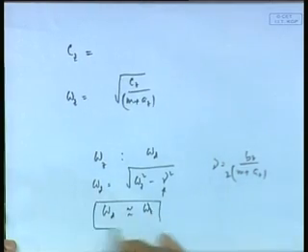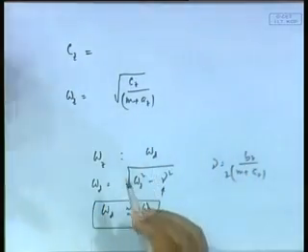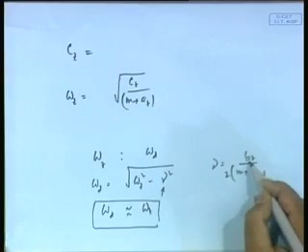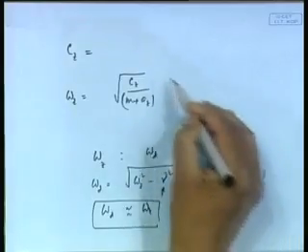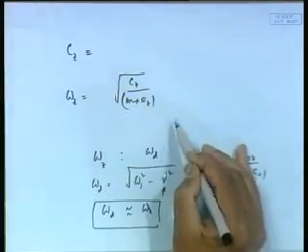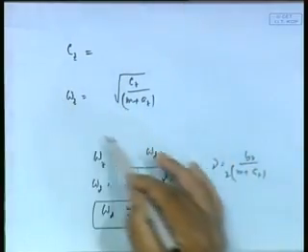So, for all practical purposes, when we study natural period and we say resonance, as you know, when omega e is omega z, it is resonating, that is this peak value. So, we can estimate the resonance by simply taking omega d to be omega z. So, our focus becomes omega z rather than omega d, which is also very useful for me, because if I had to do omega d, I had to get nu, which means I had to know Bz. Bz is much more difficult to estimate. This is very important, because if my omega e happens to be this, I am going to have a very large heave motion, right. So, natural period becomes a very important point,